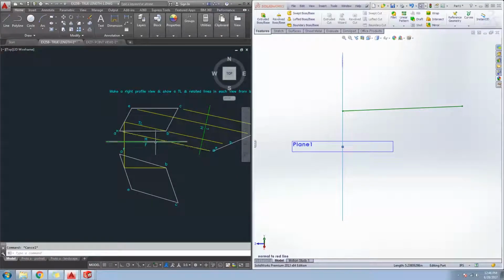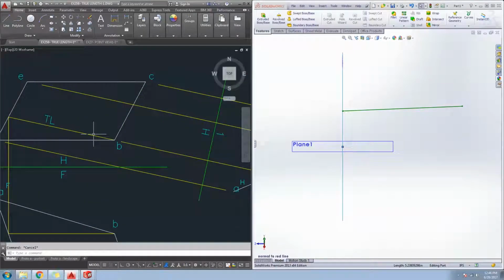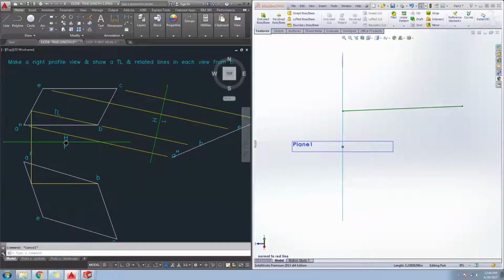alright, here's a really good question. How come I foreshortened this guy, but I left this guy connected here? Well, that's because this geometry, even though it's on the same layer as the projection lines, it's not quite the same thing. In order to state this intersection with the line AE, I have to make sure these points are connected. So I can't foreshorten them, because if I foreshorten, I lose the ability to describe to the person reading my drawing that there is actually a point that I'm talking about, a finite little point right there.